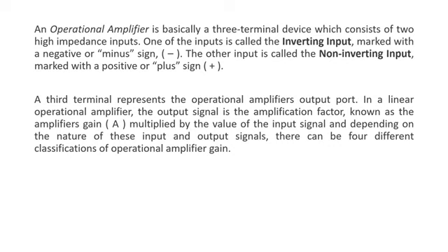Also, the gain of an inverting amplifier depends on the feedback resistance and the input resistance. I can write that the gain is equal to minus Rf by R1 in the case of the inverting terminal. In the case of the non-inverting terminal, it is going to be 1 plus Rf by R1. So if the Rf by R1 ratio is 10, then the gain of the inverting amplifier is going to be minus 10, and for 1 volt input I'll get minus 10 volts.